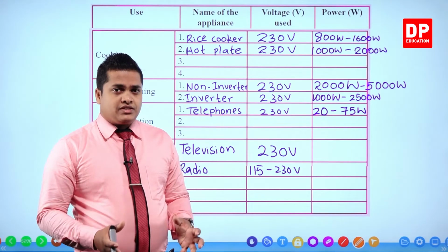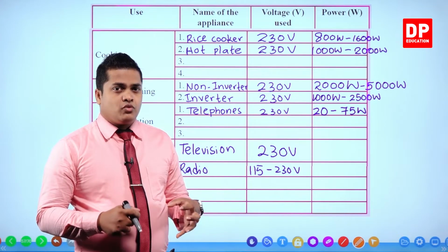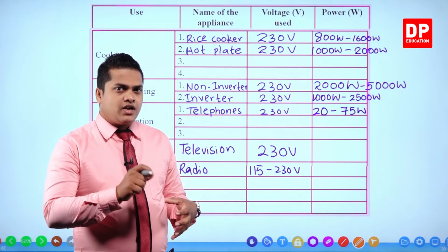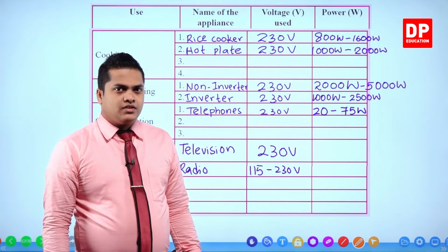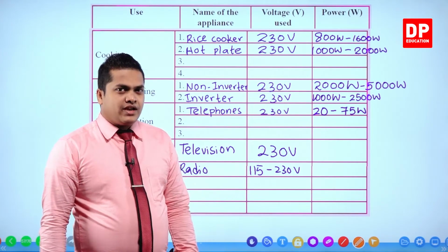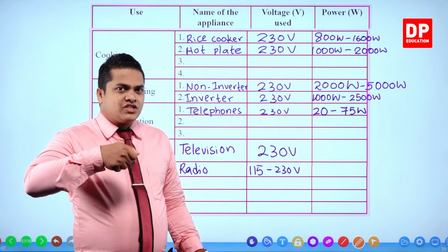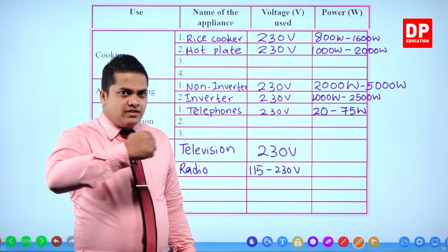Normally, even nowadays, if the instruments are imported from Japan, most of the time they may be printed 115 volts on one side and 230 volts on the other, right? So there is a small switch at the back of the radio. You can insert a screwdriver and move it here and there.